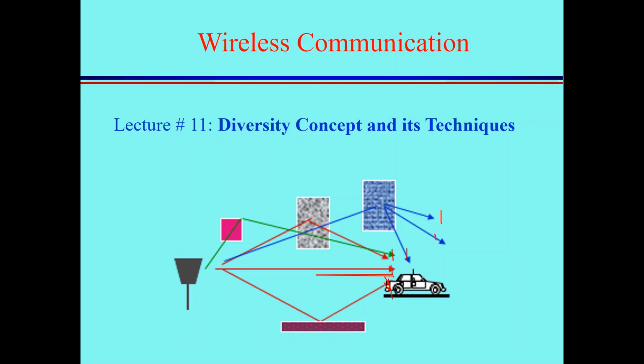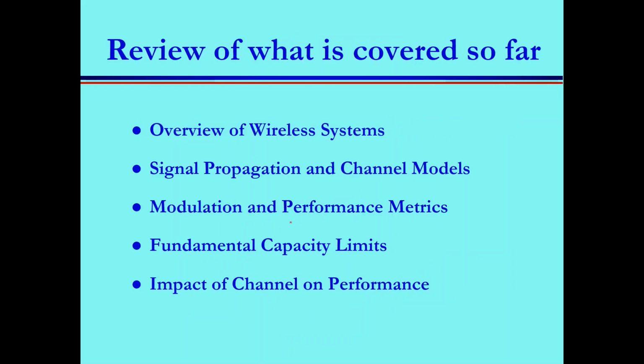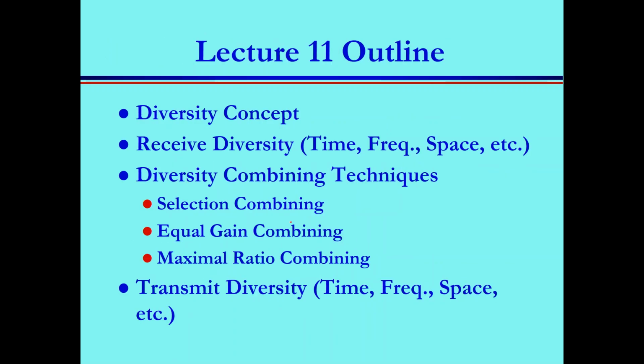When you harvest more energy, you increase the signal to noise ratio. You increase the quality of your received signal. Whereas if you don't have multipath, you just receive one path, so there are no redundant paths to protect your information. So I gave you one example of receive diversity, which is multipath diversity. Multipath when you have frequency selective, and multipath when you have a Doppler channel.